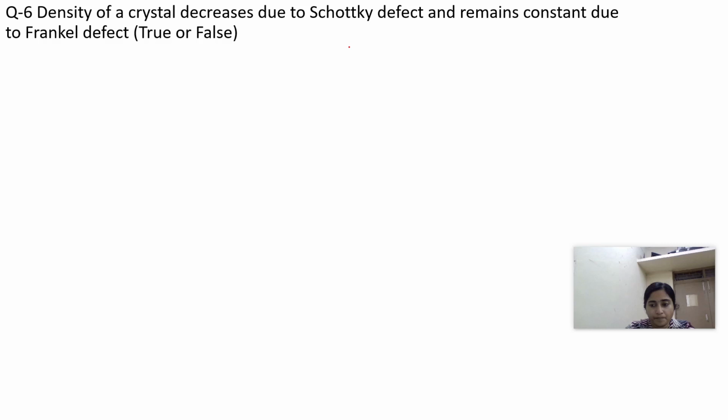Normally atoms are orderly arranged, and we get an extra diffraction pattern if they are shifted, like in Frenkel defect. If atoms go to an interstitial site, the pattern will be disturbed, and we can measure the theta angle differently. From that you can do it experimentally.